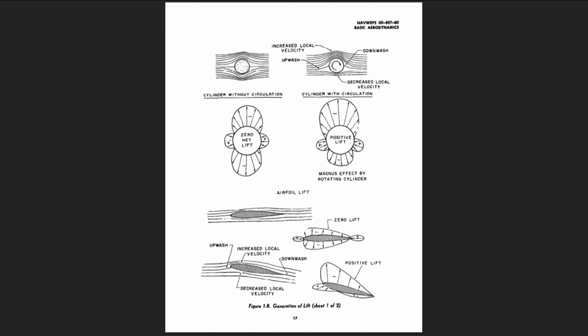This mechanically induced circulation, called Magnus effect, illustrates the relationship between circulation and lift and is important to golfers, baseball and tennis players as well as pilots and aerodynamicists. The curvature of the flight path of a golf ball or baseball requires an unbalance of force which is created by rotation of the ball.